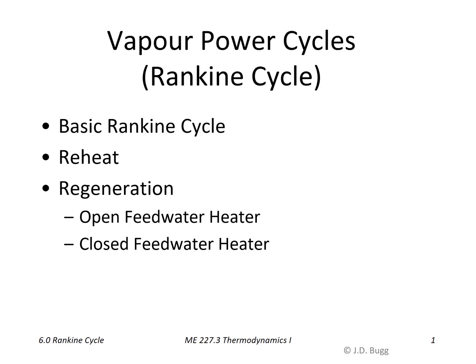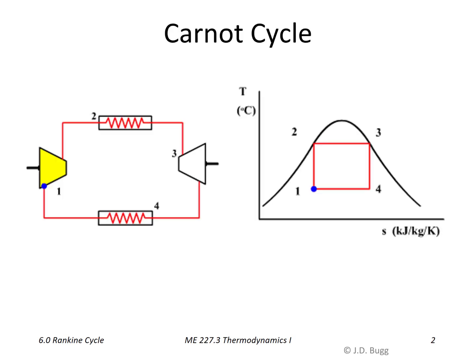Well, we're going to begin the Rankine cycle the same way as we began refrigeration. We're going to start with a Carnot cycle. Now, a Rankine cycle is a heat engine or a power cycle, so we're back to looking at the Carnot cycle in the way that we very first introduced it, and that is as a power cycle. Now, similar to refrigeration systems though, we're going to be operating with a working fluid, water in this case, which is changing phase. So we're going to be in or near the liquid vapor region.